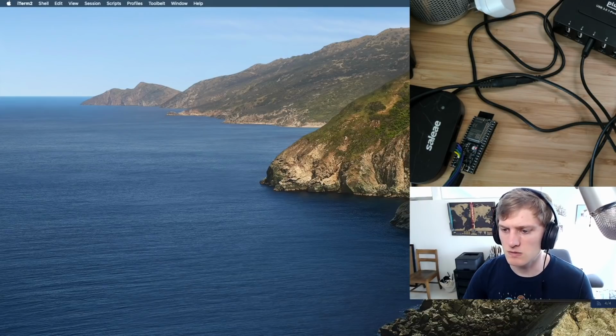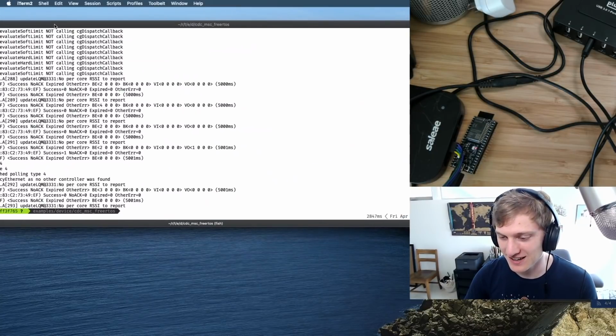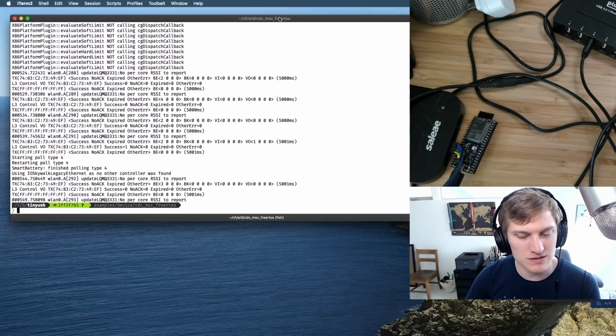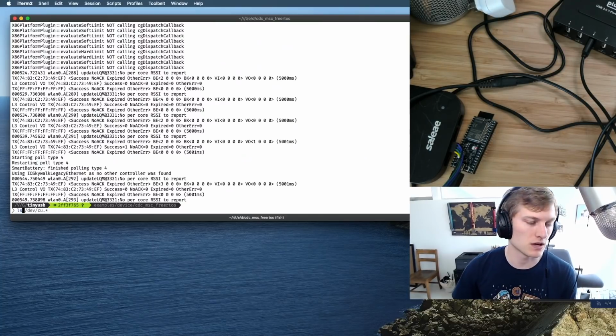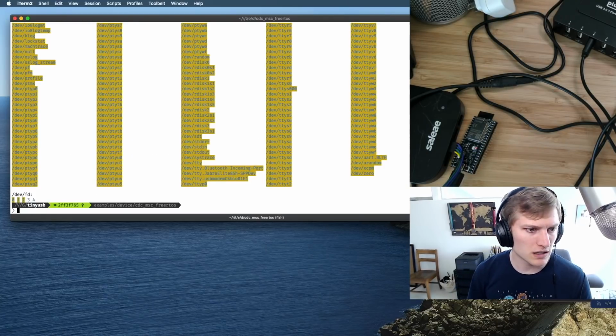Yeah, Theo says on the ESP32, not the S2, the bootloader message should be streamed at two different baud rates. Thing is, I'm not even seeing the device at all. So this stream might be turned into fixing getting the Silicon Labs drivers working. I didn't do idf.py set-target yet, but I think we're having problems that are earlier than that. Because it should show up as a serial device, and we saw that it was showing up as a serial device, but it wasn't. Now it's not even showing up as that. I can also try doing it directly.